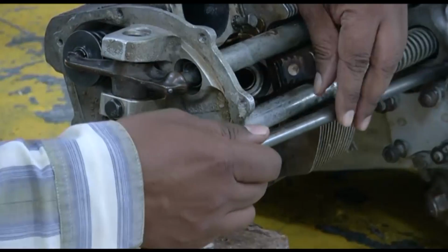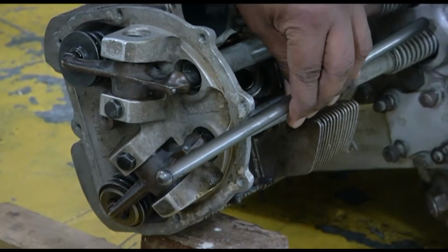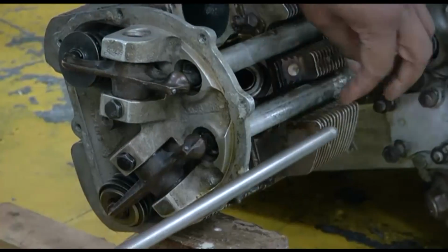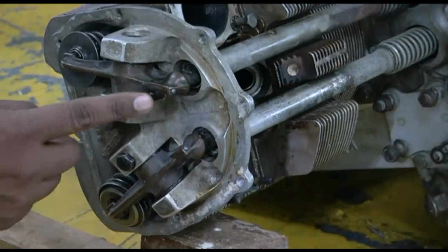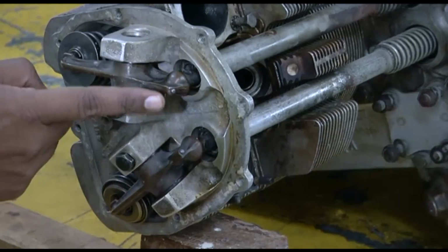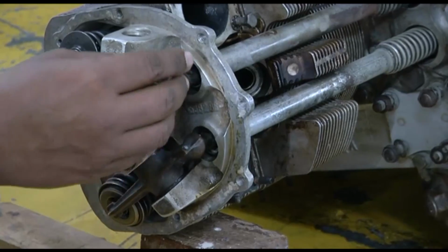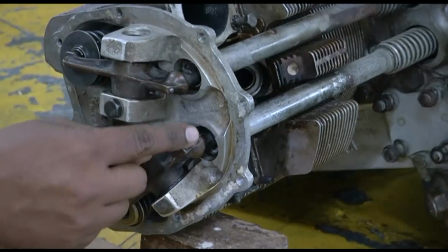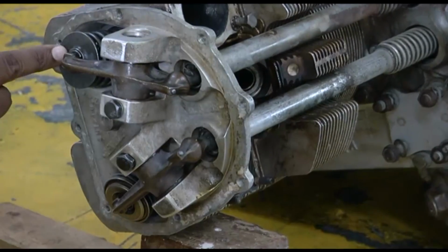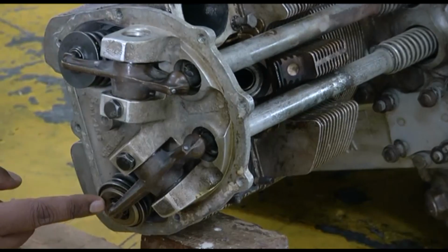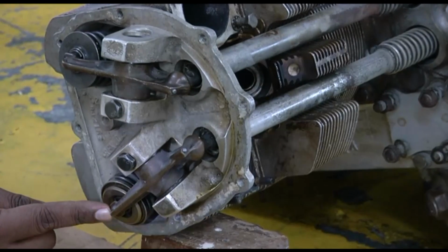So when the camshaft is moving, the cam lobe through the lifter pushes the push rod. This push rod is going through this guide. This push rod is pushed here. You can see here, when this push rod is pushed, the rocker arm, you see this rocker arm, this is being depressed. See, this rocker arm is moving. It goes up and then it pushes the valve here. You can see the valve here. See this rocker arm, it is being pushed here by the other end.